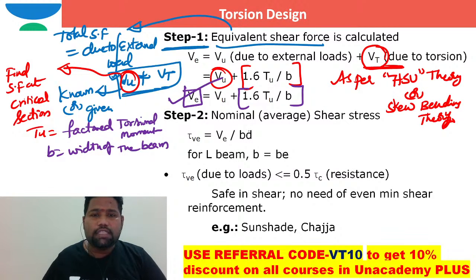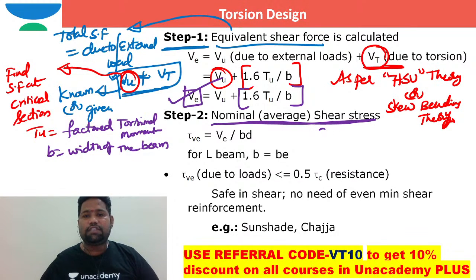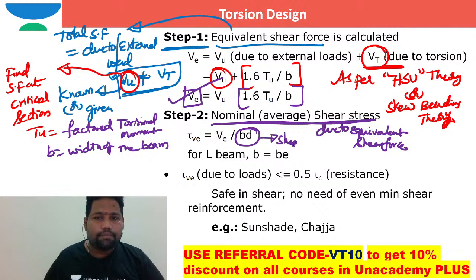Here, what is the nominal or average shear stress because of this equivalent shear force that you already know? So tau v is Ve by the shear area. I can say if it is a rectangular section, the shear area is b into d.